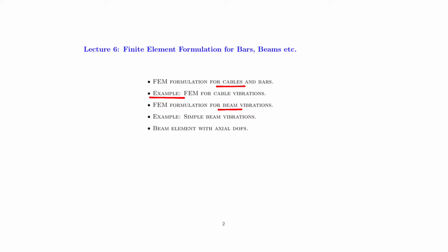And at the end, of particular interest will be to merge the beam element with basically a bar element, whereby we combine a beam transverse problem with the actual deformation of a beam, so that we get the classic 6x6 element stiffness and mass matrix for planar beam elements.